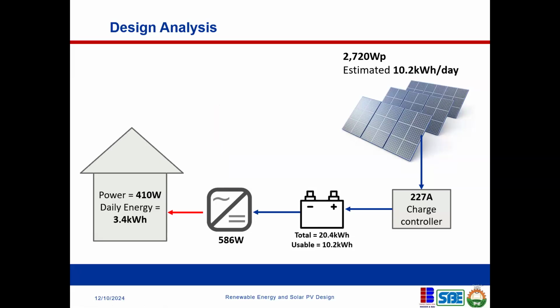Okay, but if you don't want this case, you can just use a battery inverter, in which case you're just doing one-way conversion from DC to AC. But if you're bringing in the grid, then you need to understand the architecture of your design to be able to recommend the kind of inverter that is needed. If you go to the market, you see different kinds of inverters.